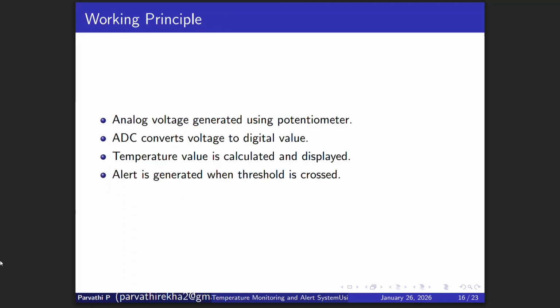Now we can discuss the working principle of the system. Here, the potentiometer generates an analog voltage proportional to the temperature. This voltage is applied to one of the ADC channels of the PIC microcontroller. The ADC converts the analog signal into a digital value.